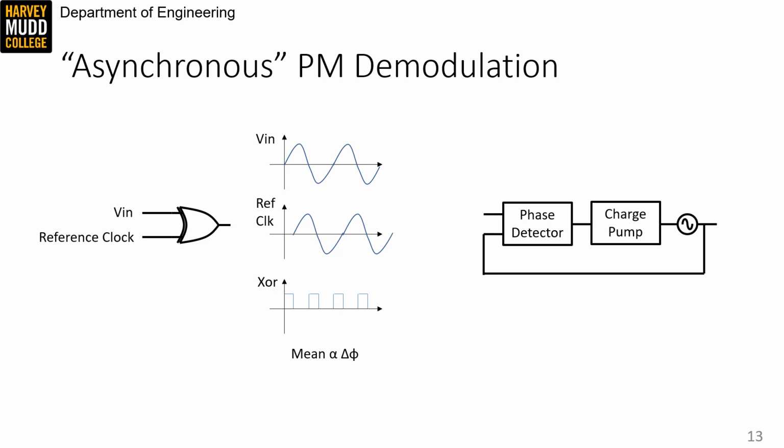If you wanted to provide the reference clock yourself, then you could use a phase detector and a phase-to-voltage converter with some filtering properties called a charge pump in order to wrap a feedback loop around a voltage-controlled oscillator. This will align the VCO with the input clock, and the control effort applied to the VCO can be used to extract changes in the input phase. This type of feedback loop is called a phase-locked loop, and we mentioned how important they are earlier in this video. There are lots and lots of other things we could say about phase-locked loops, but we are not going to right now.